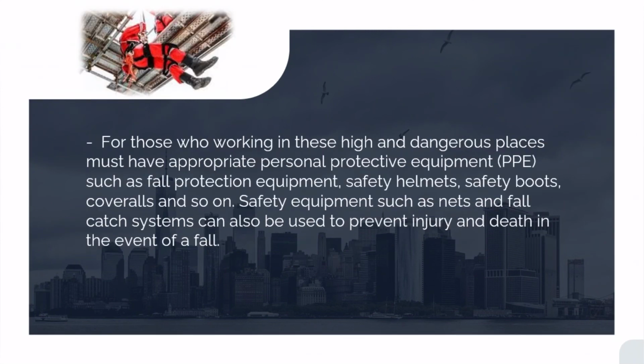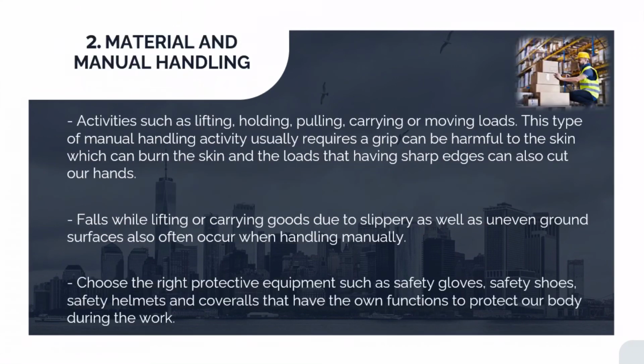So, those who work in this high and dangerous place must have personal protective equipment, PPE, such as fall protection equipment, safety helmet, safety boots, coverall, and so on. Safety equipment such as a net and fall catch system can also be used to prevent injury and death in the event of a fall.